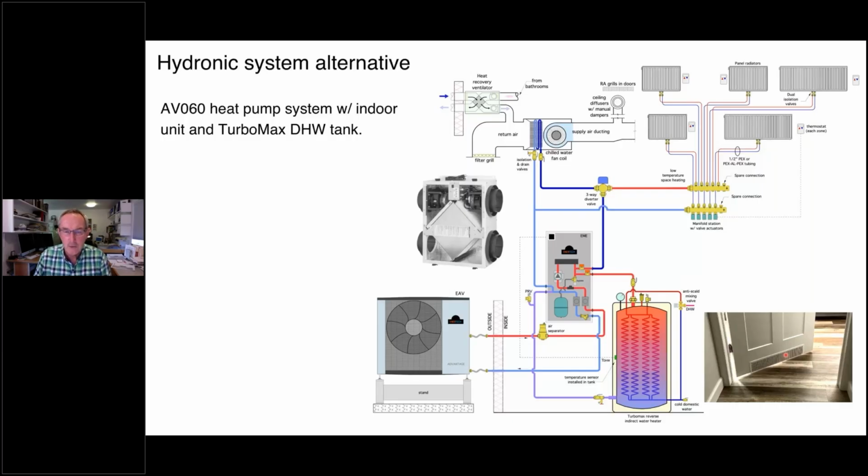And we're going to go back to a central location, and back on our schematic right here, I'm showing a filter grill. So this might be, for example, in a hallway somewhere in the building, a central location where return air that comes out of these different rooms can go to the central filter grill. And from there, hopefully it's a nice short run right back into the return side of the air handler.